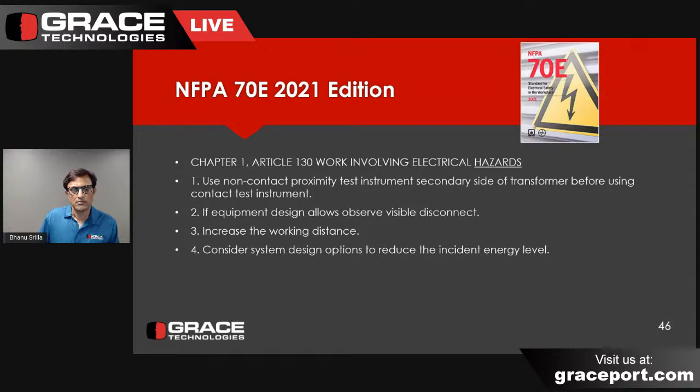Because what's happening is you're moving to high risk, because the potential injury or damage to health is no longer valid, right? It's 160 calories and I only have a 140 cal suit. The worker's not adequately protected, so here are some suggestions that were added on how you could manage that. But you have to then specifically look at it, and your electrical safety program is where you can also document these requirements, what you're going to do if the incident energy is greater than the available arc flash PPE.